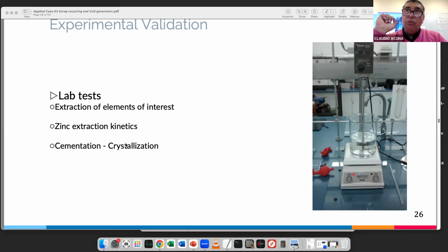But then you need to know what is the possible concentration that you have there, because if you have parts per billion, you need to have capabilities to analyze parts per billion. You need to have a guess of the concentration. So the size of the equipment and the amount that you have will depend on the analytical technique that you have. If you have atomic absorption and you want to have repeat tests, and if you want kinetic data, you are extracting in time, perhaps you're going to need 5 liters, 2 liters, because you are extracting 10 cubic centimeters a sample in time to be analyzed and get the kinetics in a single tank.